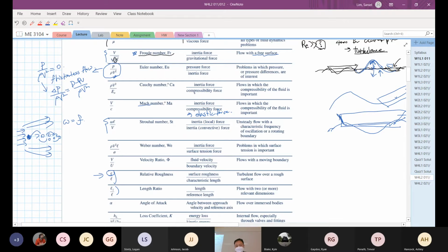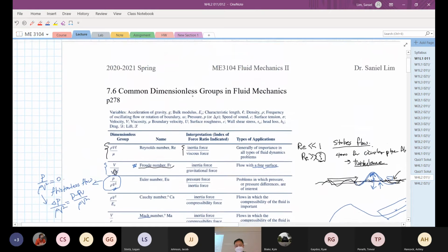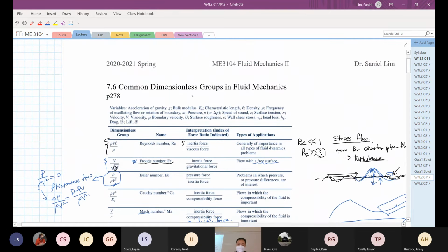So for example, a Reynolds number came up in every single example problem when we solved problems in chapter 7. That's why we always have a Reynolds number. Whenever you have a similar format of the pi term, you want to convert it into the Reynolds number. This is the easiest one you can control in the flow field, especially in the lab. So that's usually positioned on the x-axis when you design the experiments.